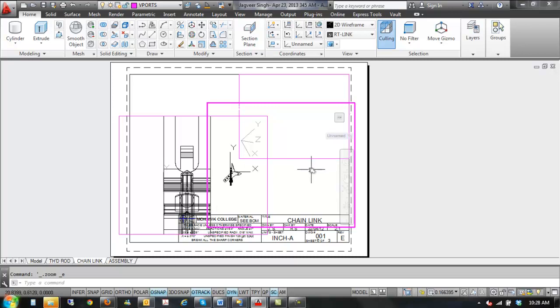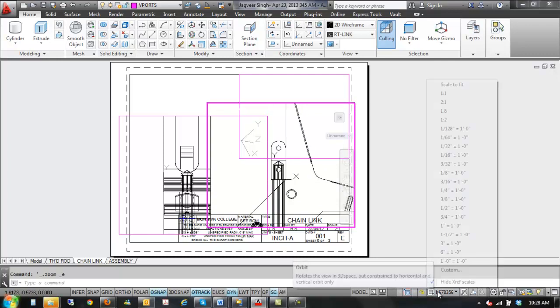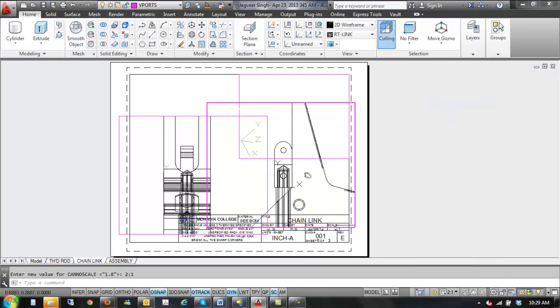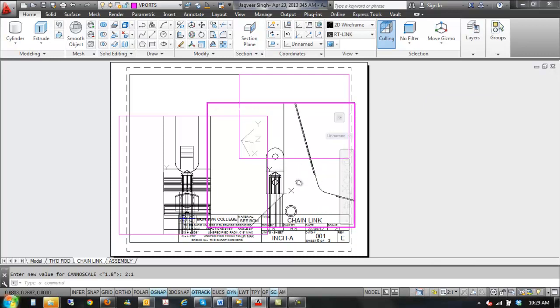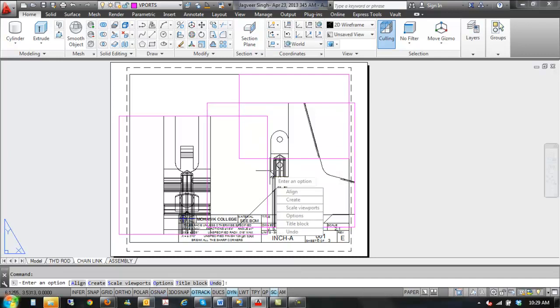Well, we can do this. There's the right side view, and you establish your scale here again. But you want to make sure that each view is in alignment. And this is where you'd have to do this extra step here. MV setup brings in a bunch of tools, and one of them is align.